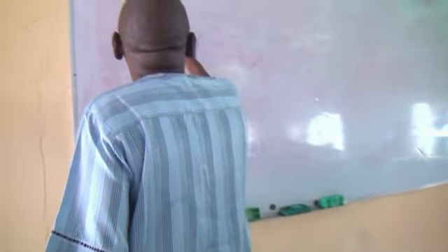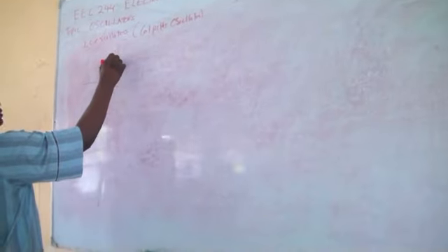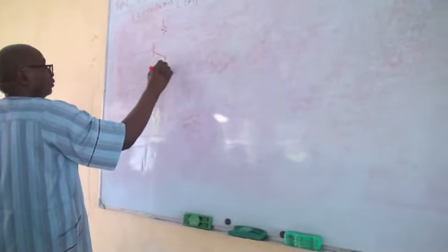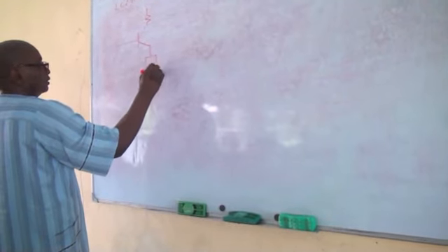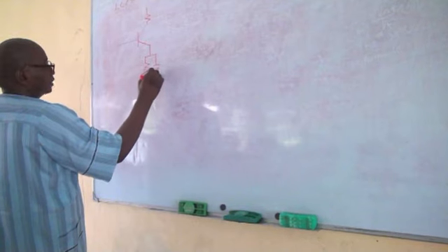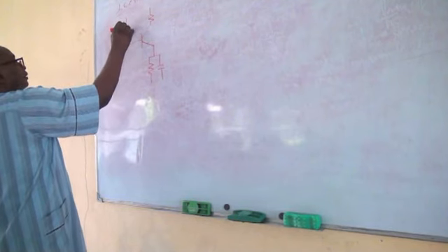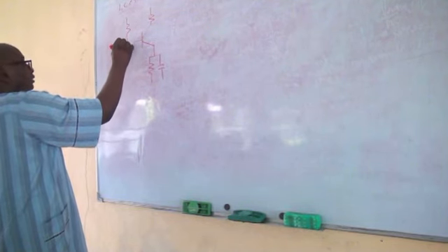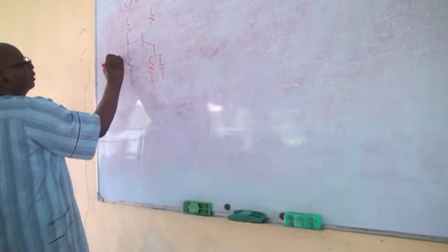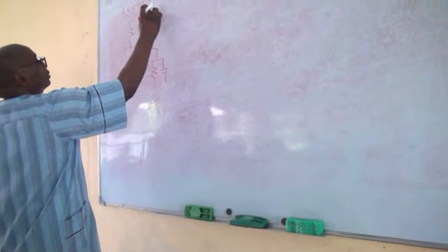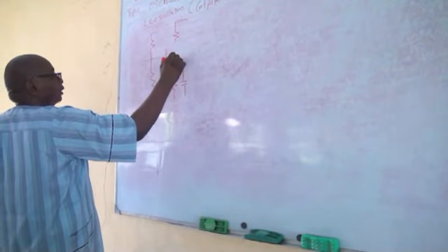I told you that oscillators use transistors, right? Yeah. This one is using a transistor. And this one is a resistor. It's connected. And the function of this capacitor here is for decoupling. And there's another resistor connected here to base bias the transistor. And this goes to plus VCC. And this is the emitter.